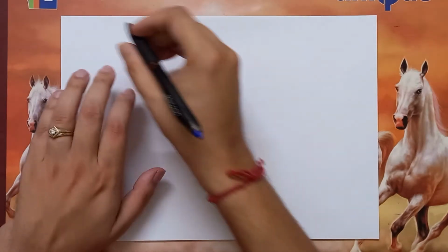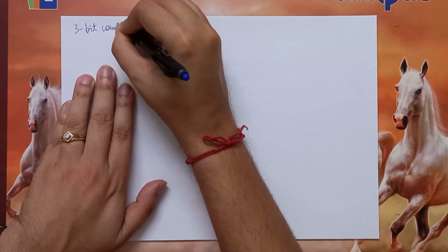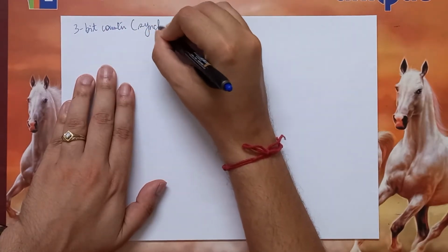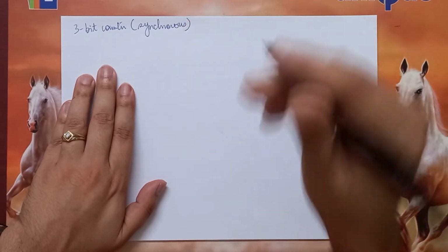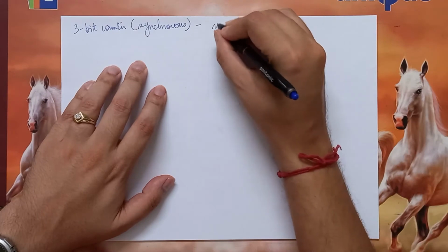So from that, let us now see how we can use that concept which we had developed for the synchronous counter to design a counter with maximum count of some number which is not the maximum possible count. So let us say we still want a 3-bit counter. We want a 3-bit synchronous counter, but it has to be a mod 6 counter.